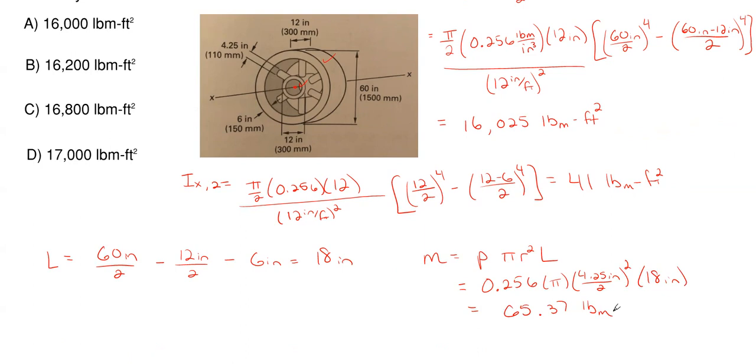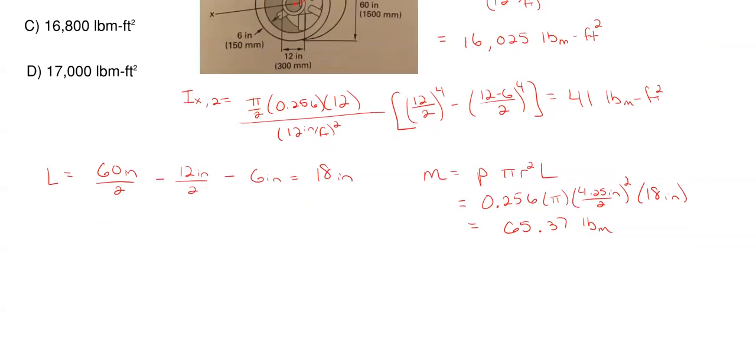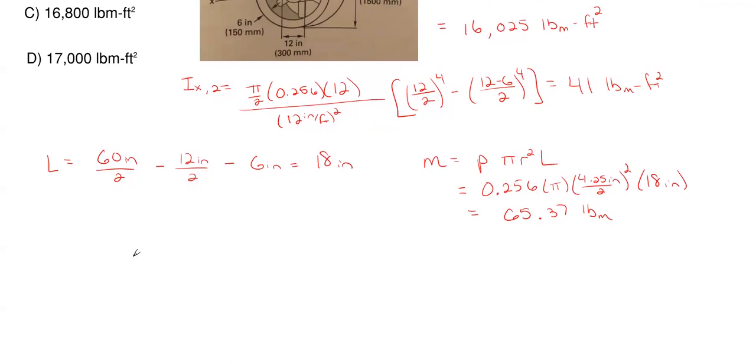All right. So we're going to have to do a little bit of difference between finding what our mass moment of inertia was for the previous two, because they were hollow circular sections. This is going to be a solid one. So for a solid cylinder, the mass moment of inertia of the spoke about its own centroidal axis will be this, and this is not going to be our answer.